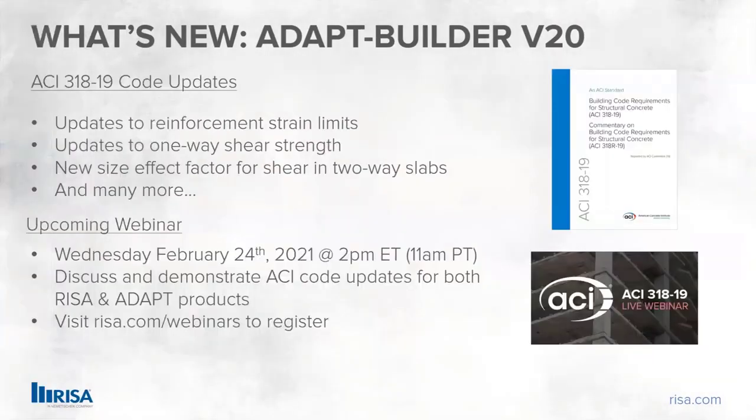Lastly, we've included the ACI 2019 design code, which has updates to reinforcement strain limits, updates to one-way shear strength, new size effect factor for shear and two-way slabs, and many more.